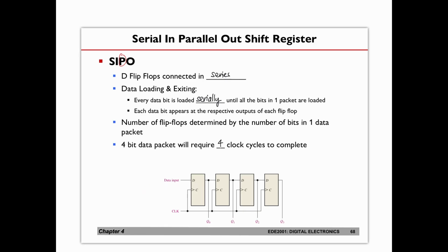So now, let's take a look at the circuit that we have here. You can see a slight difference here in that Q0, Q1, Q2, Q3 have leads coming out from them. Previously you did not have all these leads coming out, but now because you want to access the data in one shot, you have Q0, Q1, Q2 leads compared to just now, whereby you only have a Q3 lead. From a circuit point of view, the only difference is that at each flip-flop output, the output is being connected to the external device.